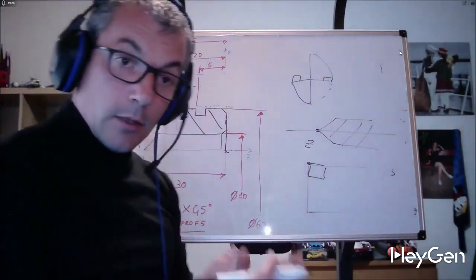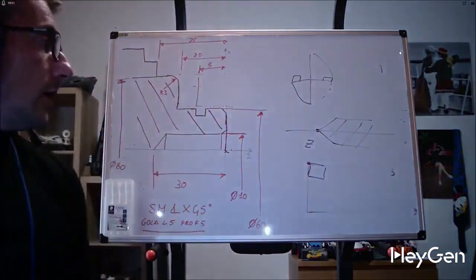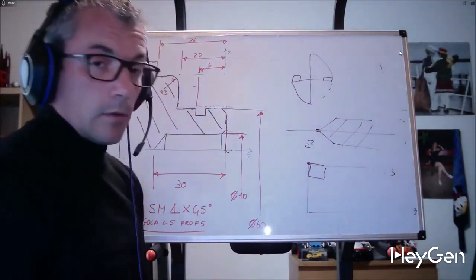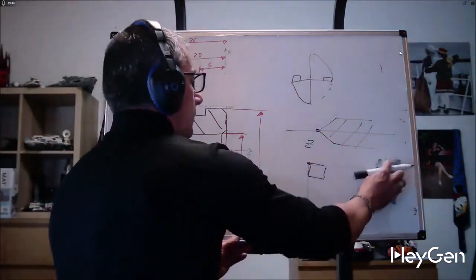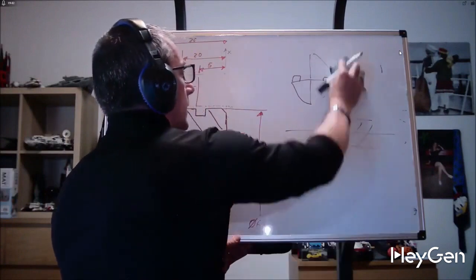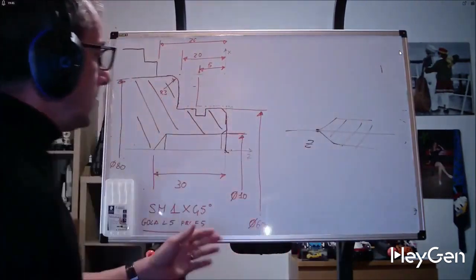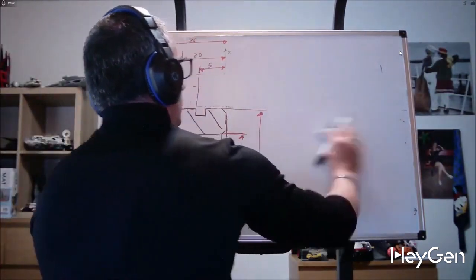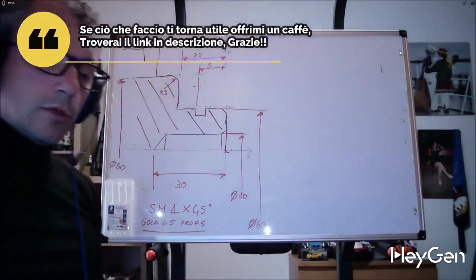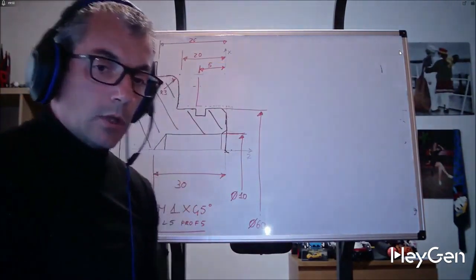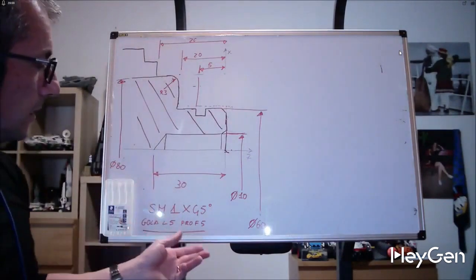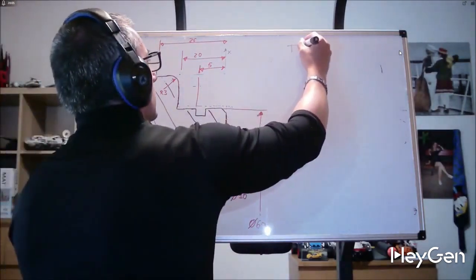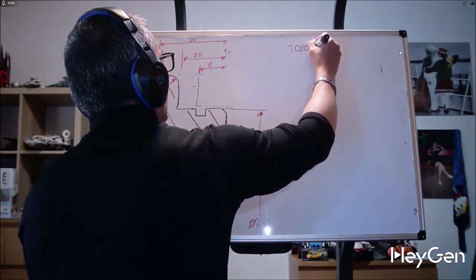Okay, now we stick to the classic, to not complicate life too much. On the contrary, we make it much easier. Trust me. But let's stick to the classic and drill with a 10 spiral bit. Nowadays the bits, unless using special materials or very long holes, can drill a hole with a diameter of 10, depth approximately 30 millimeters. Therefore I call my tool T3, T0303.